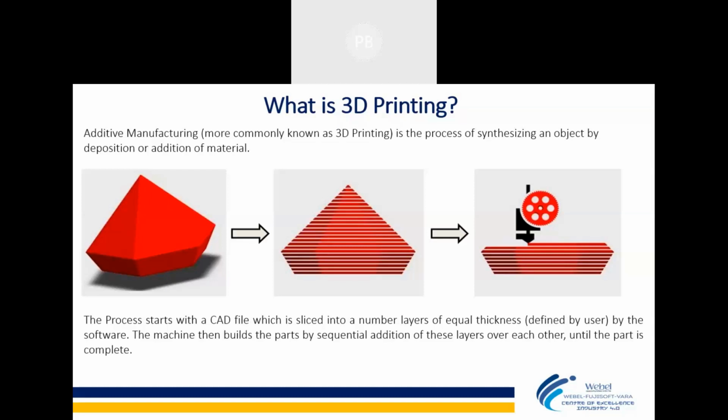We can touch the thing, we can remove the part, that kind of thickness will be there, a hardy substance. So whenever you get something in the Z direction, into the thickness, that comes into 3D. Here also, we will design something in CAD software, put it into the machine, and the software will cut it into multiple layers, maybe 100, 200, 500 layers. Now the machine will deposit each layer, layer by layer, and your product will be formed, going from a CAD file to an original product.